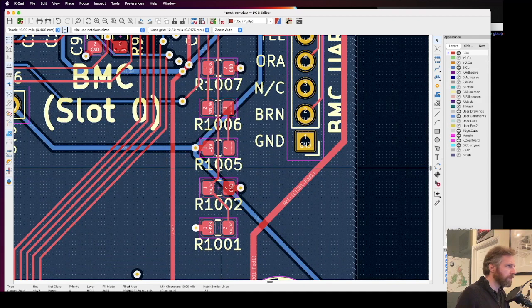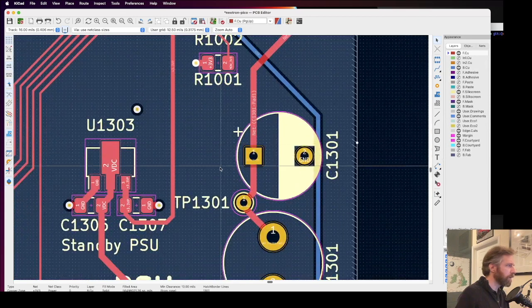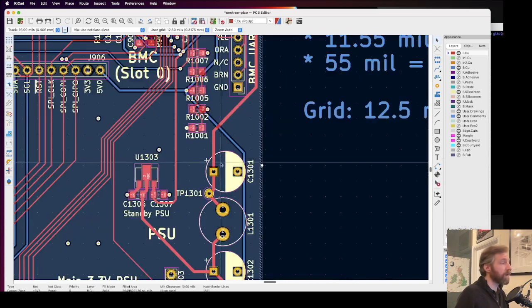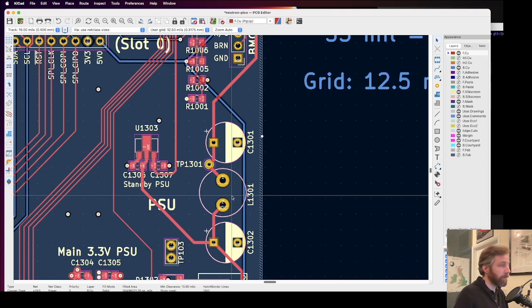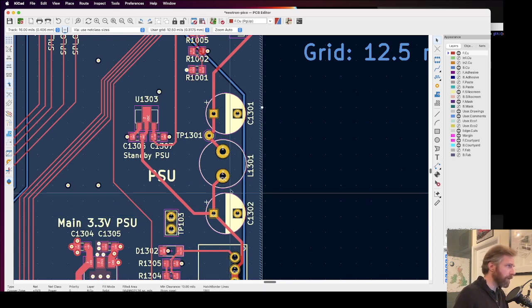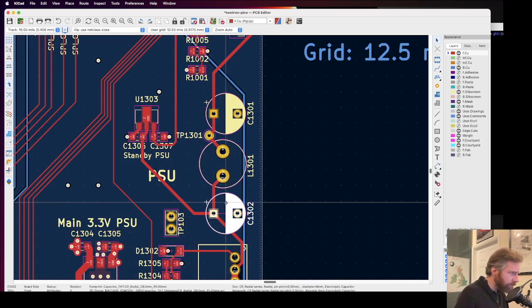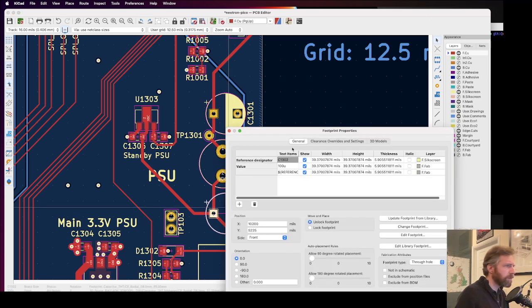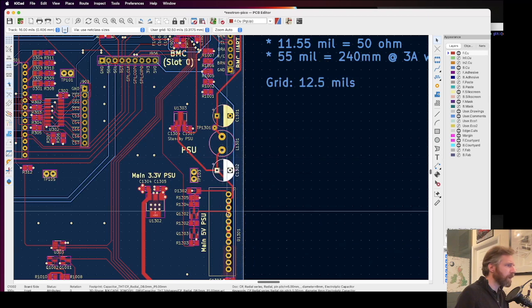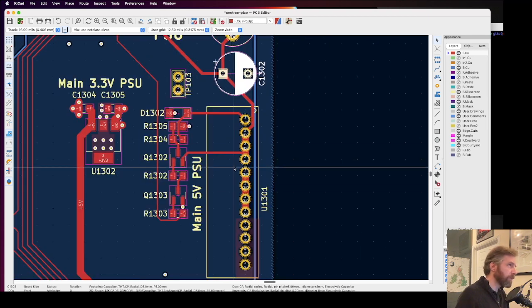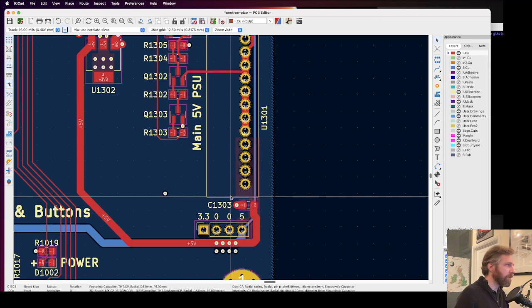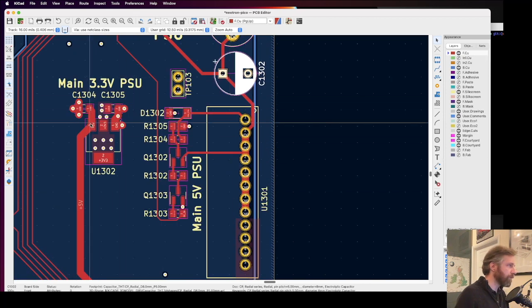Scroll down, those look okay. Power supply circuitry. So we have 12 volts come in. It goes through this pi filter, cap, inductor, cap. They're big 100 uFs, I think. Yep, 100u. And then it goes into this Monsun 5 volt 3 amp switch mode power supply module. So we get a nice 5 volts out of here, and then we run the 5 volts up to this 3.3 volt regulator, and then this powers most of the board.